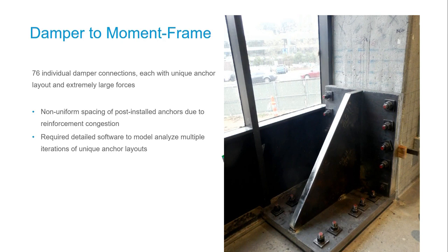And obviously when you start having weird spacings, okay, these bolts are at 6 inches, these bolts are at 5, now we have the bolts spaced at 8. How is that really going to distribute your forces? You can't really assume anything will work too well that way.